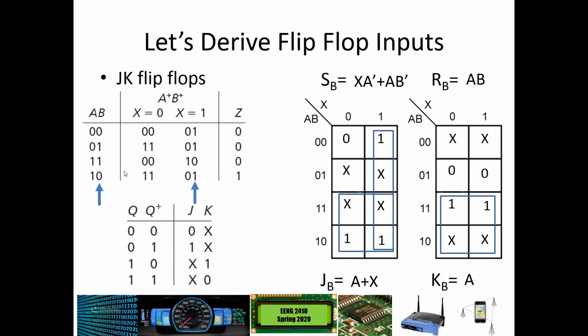And for your second project, don't think about using SR flip-flops because JK will give you better logic implementation in every possible case. So we cannot guarantee with T and D flip-flops that T is always going to be better than D or vice versa, but we can guarantee you every single time that JK flip-flops will give you equally complex or simpler logic than the SR. Okay?